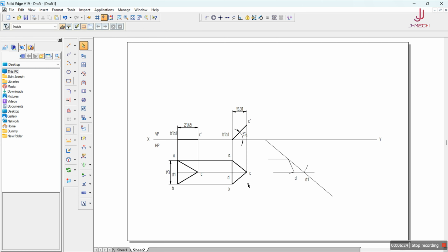Now I have to copy this particular triangle out here. For that I will press hold the control key and press the lines one by one, or else you can entirely select this line, then press hold the control and press the line. It will select the namings also, so you can do any of the methods that you want to copy. I'll press hold the control key and drag this particular triangle out. Once I drag it out, I will trim the extra lines that are not necessary.